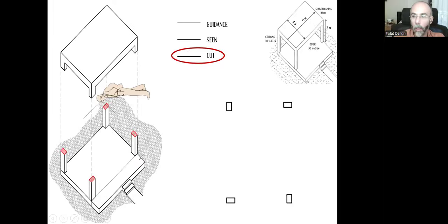So let's have a look now. This is what we do. We start here again from this corner, and first create that column for 30 by 40 centimeters with thick lines because they are cut surfaces. And then I need to go for 4 meters in this direction, which gives me this outer corner of the second column, that one. And according to the position that I see on the left side, I need to create one more rectangle positioned like that.